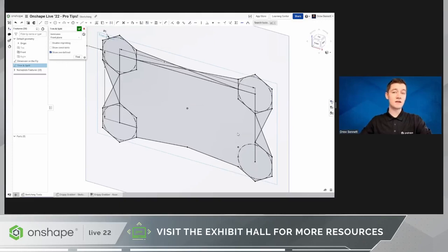Now with that in mind about the dimensions, the split tool is arguably even better, and I'm going to show you why. So back up in that same dropdown is the split tool. So let me grab that real quick. And the way the split tool works is it's going to preserve the elements, but it's just going to chop them up. And it's going to do that at common snap points. So if I hover over this line, I will then be able to go to its midpoint where it collides with the other line. I can split it right there. And now the line is half as long. Let me split this other one real quick as well.